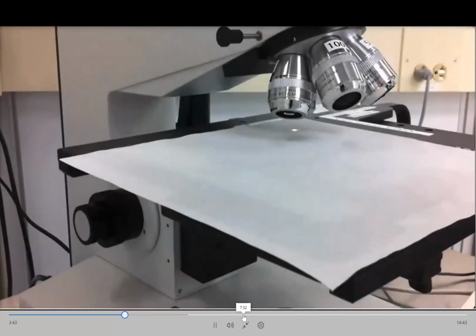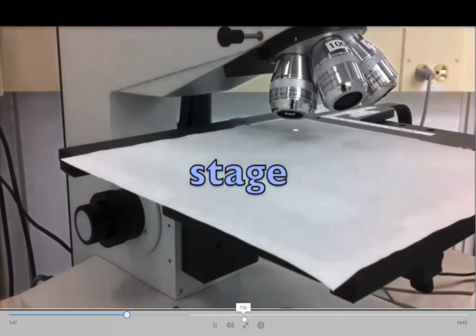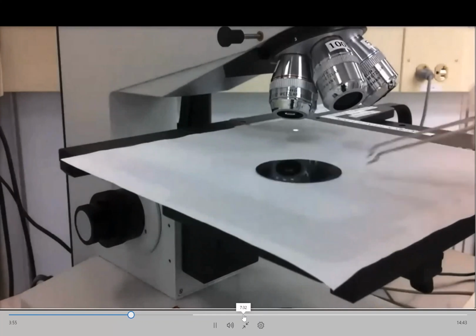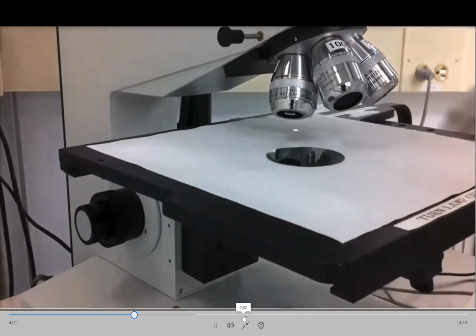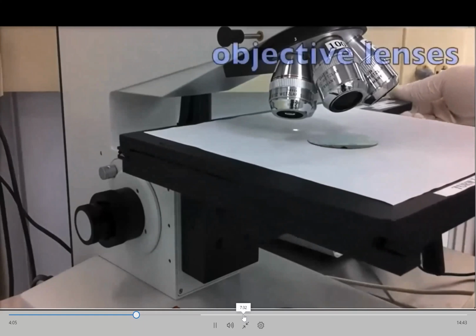Before we can image a sample, we have to load it onto the stage. Samples should always be loaded onto a clean room napkin, which rests above the stage. This protects the microscope stage. Once loaded, grab the napkin and center it above the stage. After this, use the stage adjustment handle to roughly position your sample below the objective lens of the microscope.